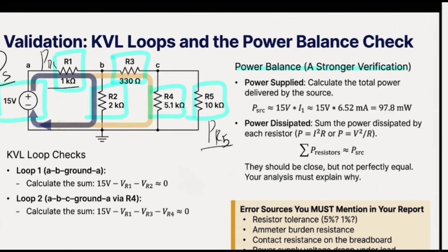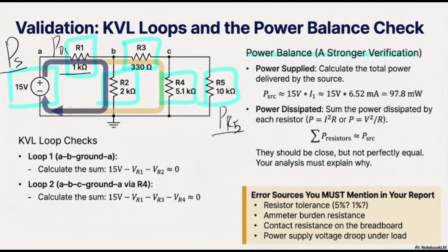So at this point, you can simply find the power source. Probably we are going to have the simulation related to that. By the way, it's going to be so simple. If you would like to do the calculation, you can consider those voltages at the nodes, write down 2 KCLs, then use Ohm's law to find all of the voltages. But if you do all of the calculations, your power source is going to be what? It is going to be voltage times current. So it's going to be this amount of milliwatts.